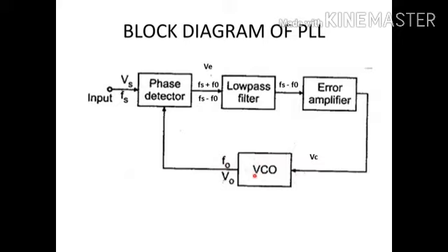It is called a voltage controlled oscillator because, depending upon the applied control voltage Vc, it is possible to shift the frequency of the oscillator either in the positive or in the negative direction. That is why this VCO is called a voltage controlled oscillator. Now returning back to this part, the phase detector accepts the input signal with the frequency Fs, and initially the signal from the output of the VCO, which is F0. The phase detector is fundamentally a multiplier